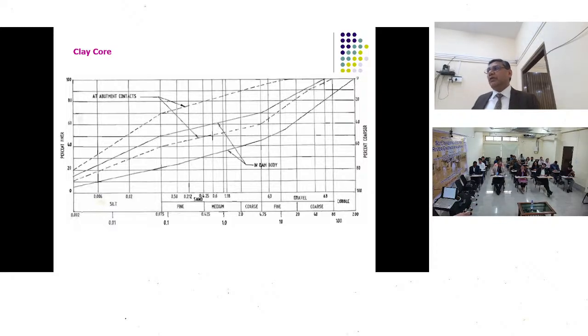So stockpiles are always checked well in advance. So it was known that stockpile A, B, C and D are going to be used for the next 1 month. So these tests were carried out before 1 month. The stockpiles are ready 1 month before. The borrow area is maybe ready 3 or 4 months before.